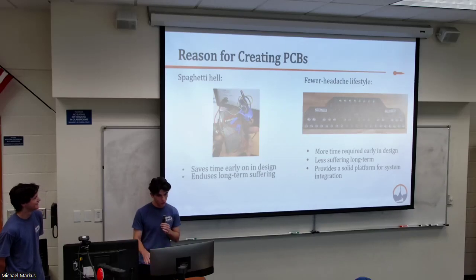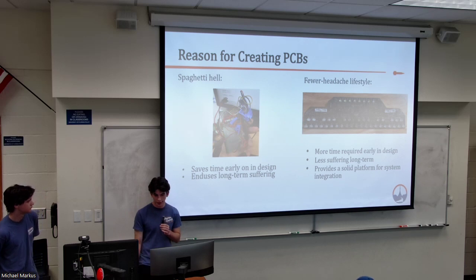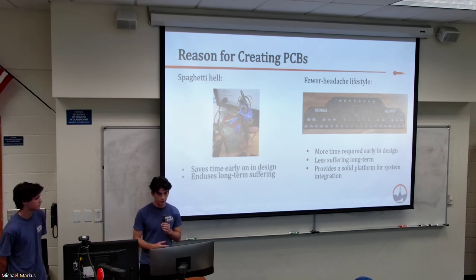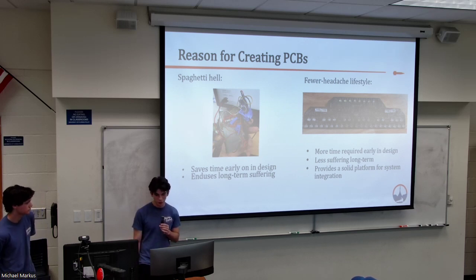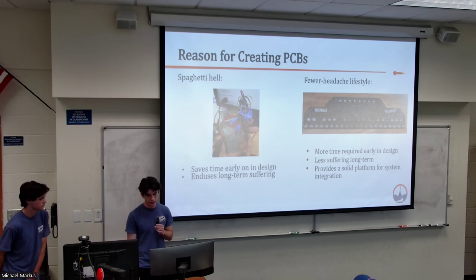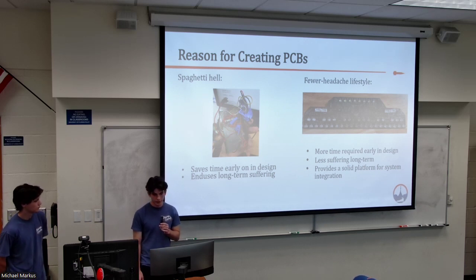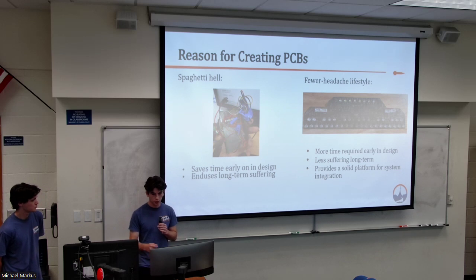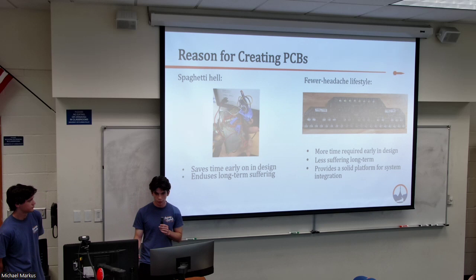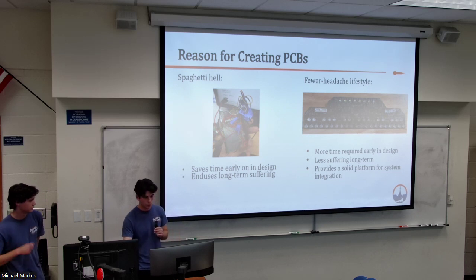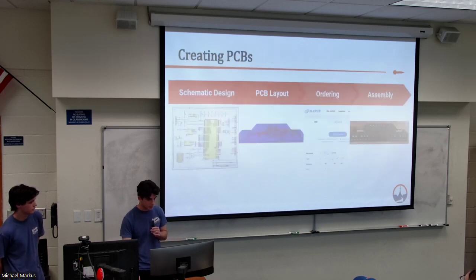Really, you don't want to prototype on proto boards with lots of wires if you can. It gets very confusing and debugging becomes a nightmare. And you really, really, really don't want to do it. It does require, as that says, more time earlier in the design, but it's really 100% worth it. Because then if something's broken, you just probe around with an oscilloscope, maybe you have some status LEDs, you can look at the board and see what's working and what's not working. And then you go back and you iterate upon your design.